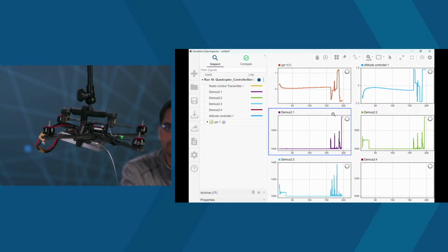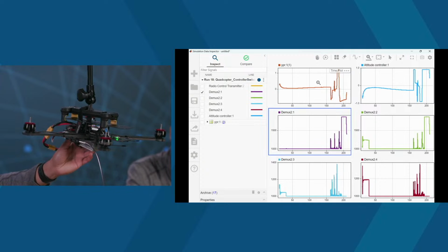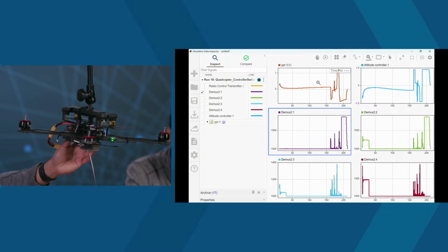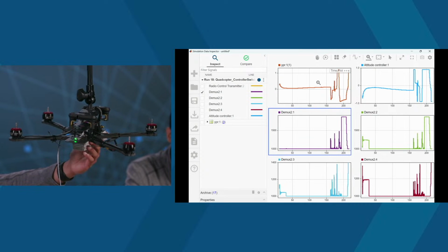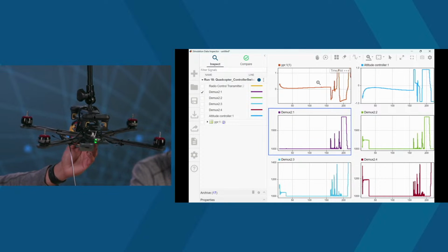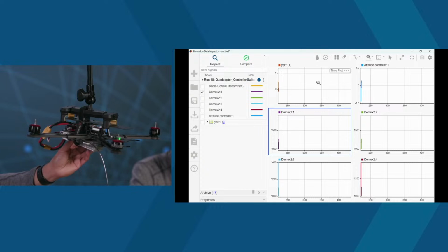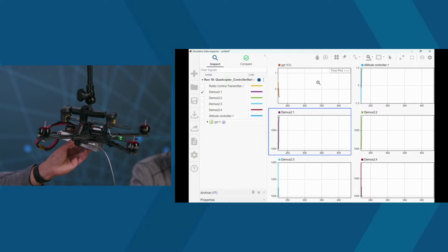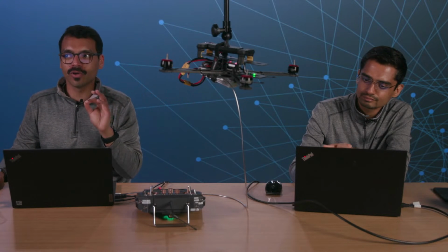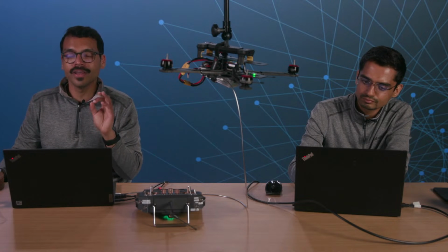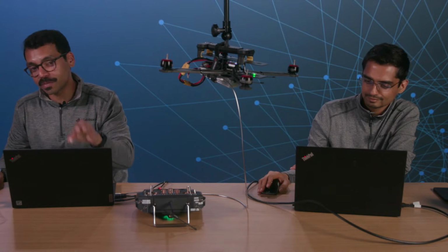All right, so yaw on top gives me my current yaw value. I'm going to change my yaw and get it to 0. You'll see all my motors have fallen down. Now if I start yawing this side, 2 of my motors will turn on, saying, hey, come back. And if I yaw to the other side, where my yaw falls under 0, the other 2 motors will start shooting up. How cool is that? This is a way for you to make sure, while you're connected, that your attitude controller knows what it's doing and your motors are going to perform the way you expect.